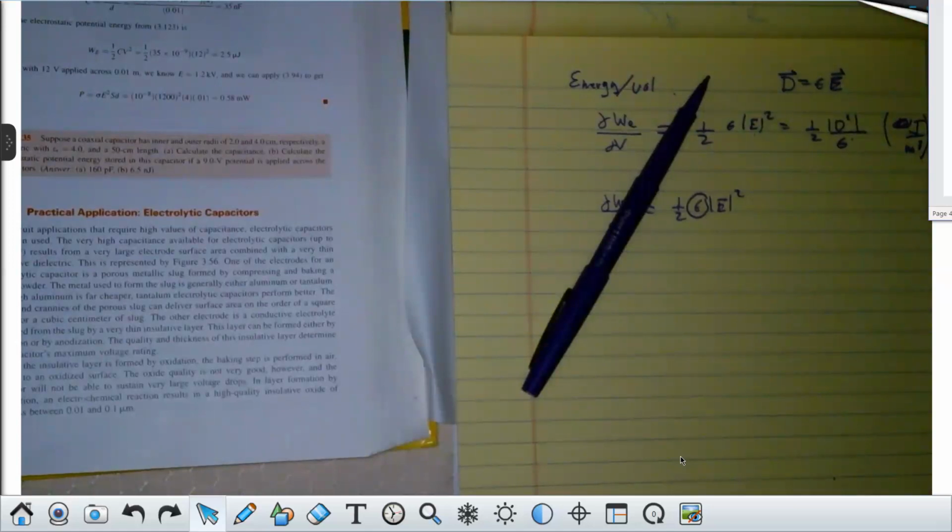With dielectric materials, you would like the breakdown electric field strength to be much, much greater than that. Instead of 3 million volts per meter, maybe 300 million volts per meter, like with a good insulator. Maybe 10 to 15 times, or maybe 100 times what the atmosphere has. Do you all follow me? So that would allow much more energy to be stored per unit volume before it arced over. So that's something called the electrical breakdown strength of an insulator or a dielectric. And you want it as high as possible. And that's also something that materials engineers try to create, these materials that will have enormous breakdown strengths.